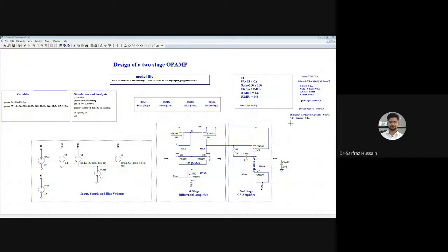We can give feedback to the op amp. There are a positive and a negative end. If you consider this op amp as an inverting amplifier, you connect that to Vin and give a feedback resistor to it, then you check. These are the things we can do, like checking if there is an offset.